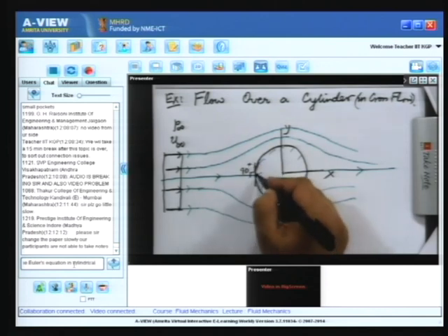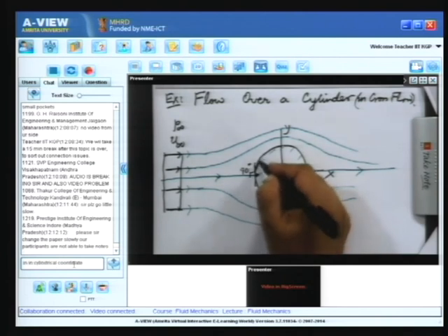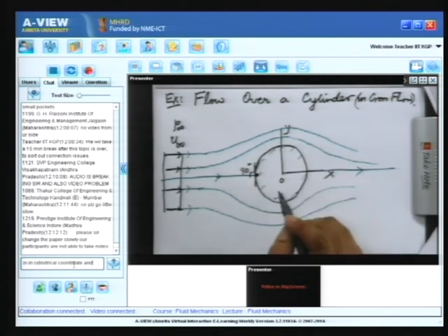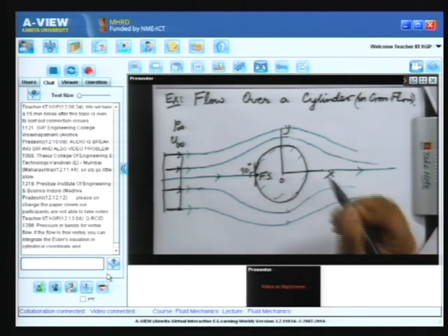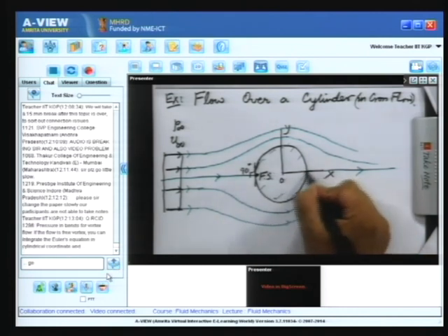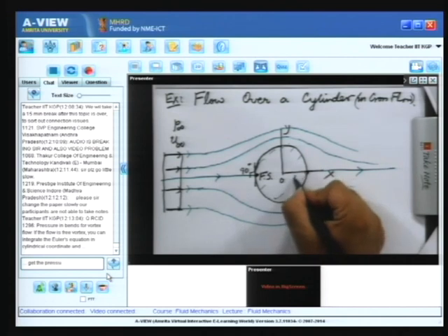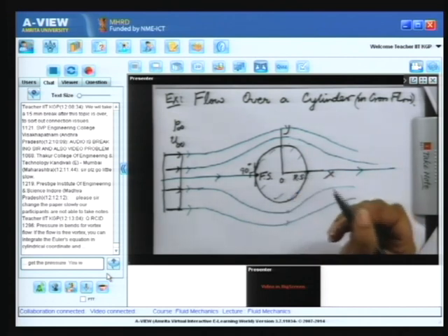So, this point will be a stagnation point where the velocity is 0 even in inviscid flow. At other points along the surface, the velocity will not be 0. So, this is what we will call the forward stagnation point, I am denoting by Fs, and similarly here you will have another stagnation point which we will call the rear stagnation point. I am indicating that by Rs.